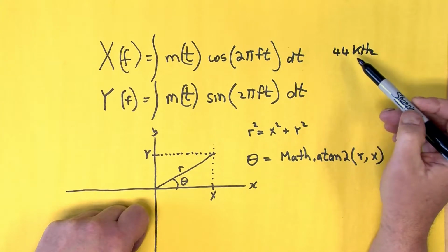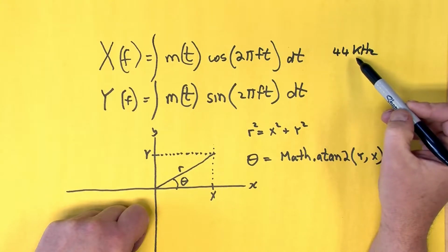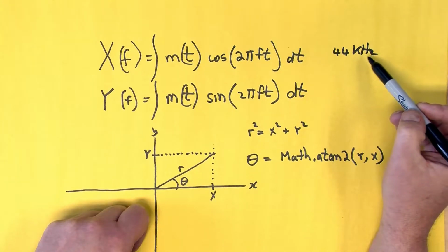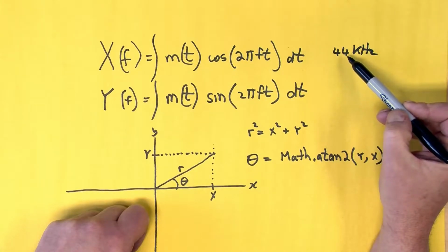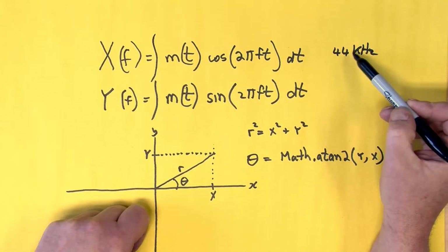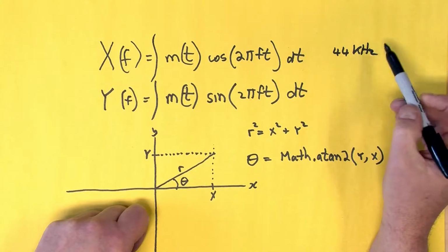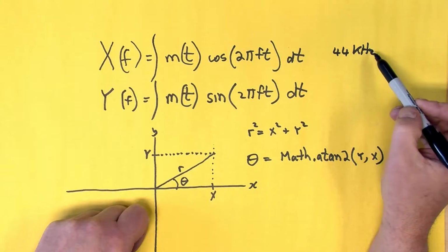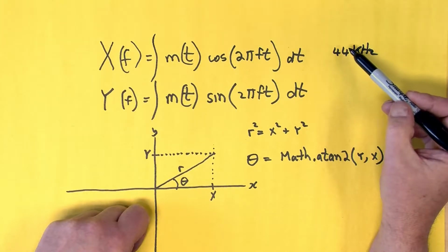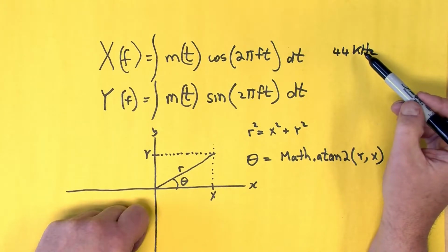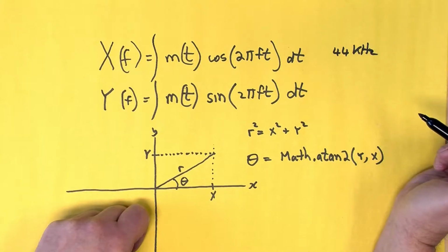And it turns out for every hertz of bandwidth you need twice as many samples per second. So in theory, this could handle audio up to 22 kilohertz, but in reality, there's probably a bit of leeway in most systems, so most audio systems go up to perhaps 20 kilohertz on a good day.